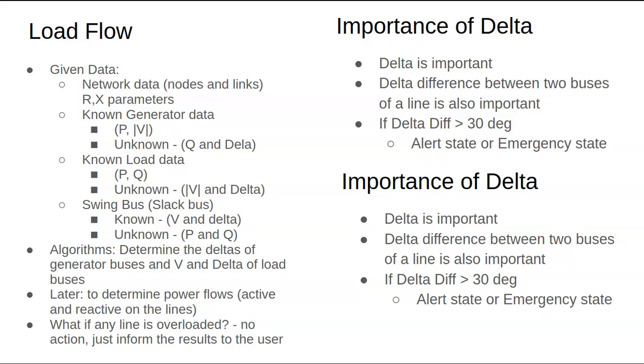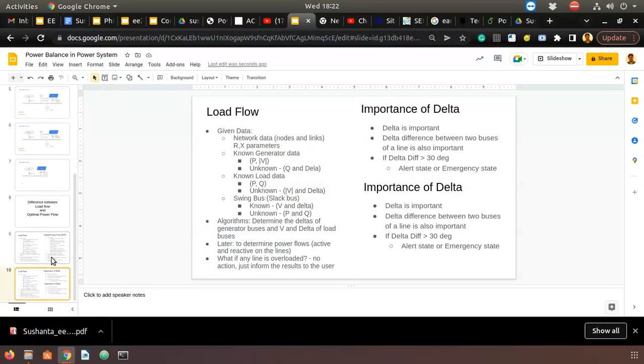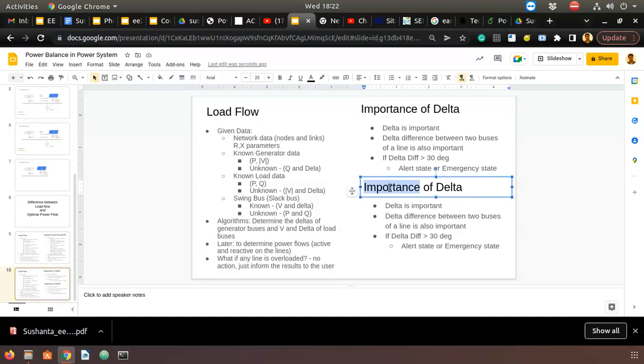But if we know that losses of 50 kilowatt are happening, the contribution of each generator, how much each is contributing to the 50 kilowatt, that should be the objective of load flow. So what you are talking about is called loss allocation.